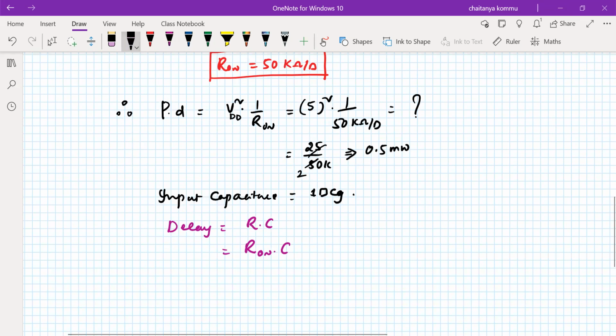I think it's at the input side, right? So better we calculate the pull down network related capacitance of A. So A is the input capacitance. Of course, it depends upon different parameters, but for the time being I don't want to calculate this, because various factors will depend on that. So this is the straightforward way to calculate the power dissipation and input capacitance of the gate.